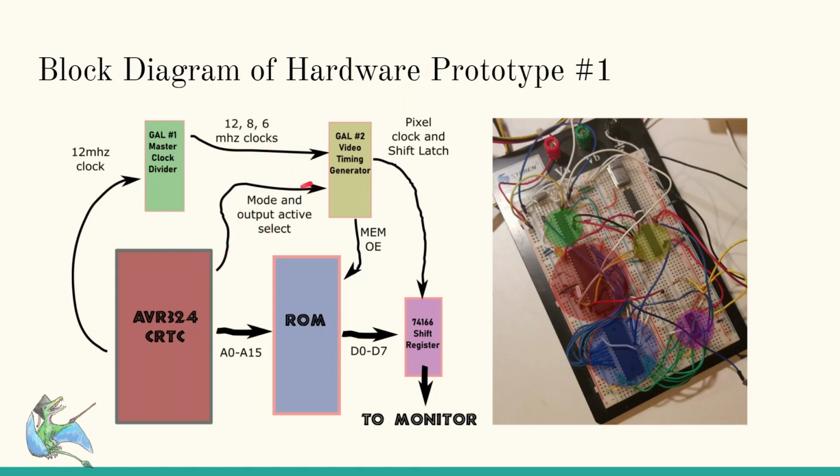And then there's some control lines that run from here to here. And when we're in an active line, one of these lines basically says, okay, start outputting pixels. And it's this device that, on the correct cadence, which is set by the CPU, once per character cell meaning 8 bits of pixels, sends the necessary read to the ROM, which this is counting up synchronously with that.